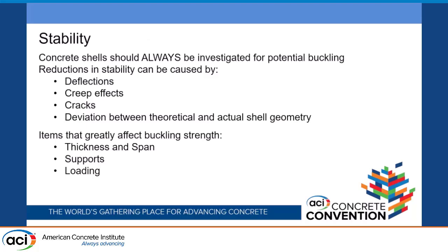Stability. So most of the time when we're doing concrete design, how much time do we spend on stability? If you're designing a concrete beam, how much time would you look at stability in that beam? Zero. Yeah, that's right. Well, stability is one of the number one things that we look at with shells. They are so thin and they span large distances, so stability becomes a huge factor in analysis and design.